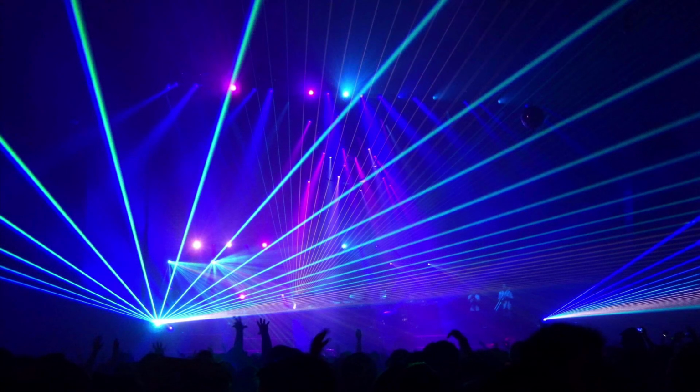We'll talk about this more later in the course, but just know that each lighting fixture is different. Some only require a single channel, some 5, some 100. It just depends on what kind of device you're working with and how many points of control it supports. This concept is sometimes referred to as a light fixture's personality. No matter what though, every fixture always has a way to set an address that represents the lowest numbered control channel for that fixture.